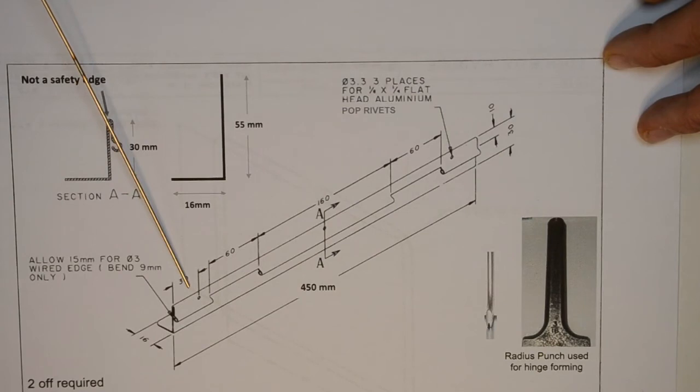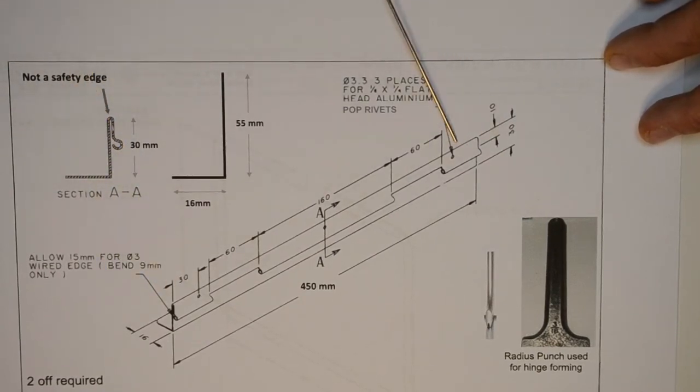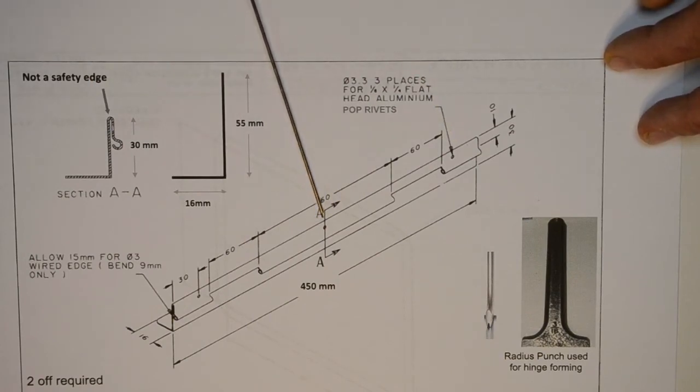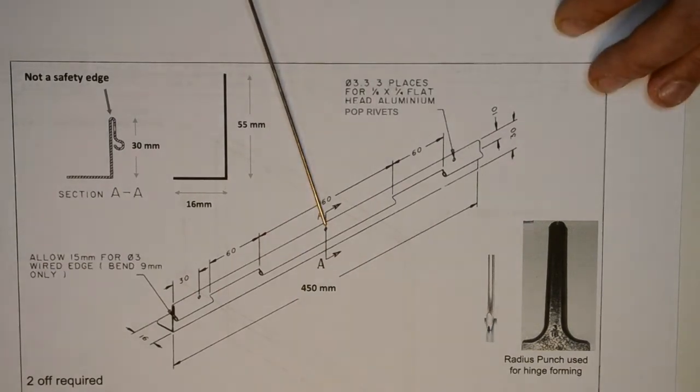And so, by convention, we therefore assume that this one, as they've not told us otherwise, is also spaced at 30mm. This one here has no dimension at all, but again, by convention, the assumption can be fairly made that this will go in the centre of the hinge unit that you've produced.